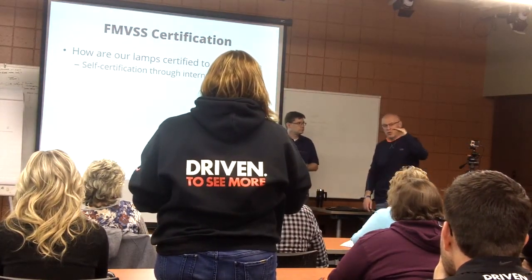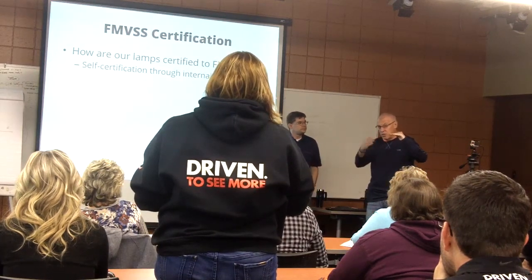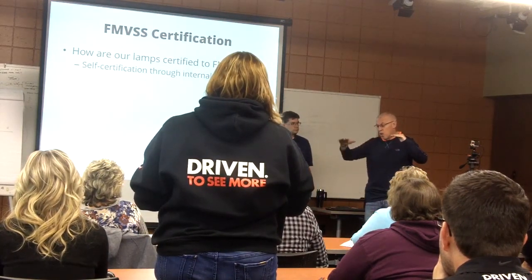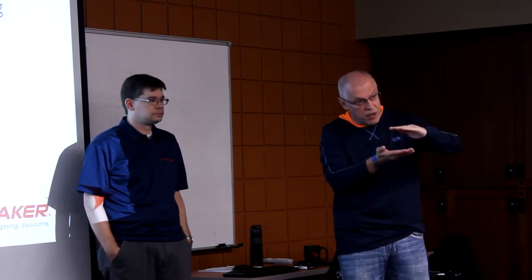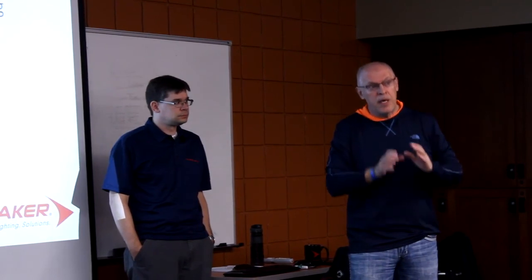There is photometry testing, which is performance on the road, and there is also environmental testing, which includes vibration, salt chamber, humidity, high temperature. All of that you have to pass and put in a document, and that is the document which goes with the lamp.